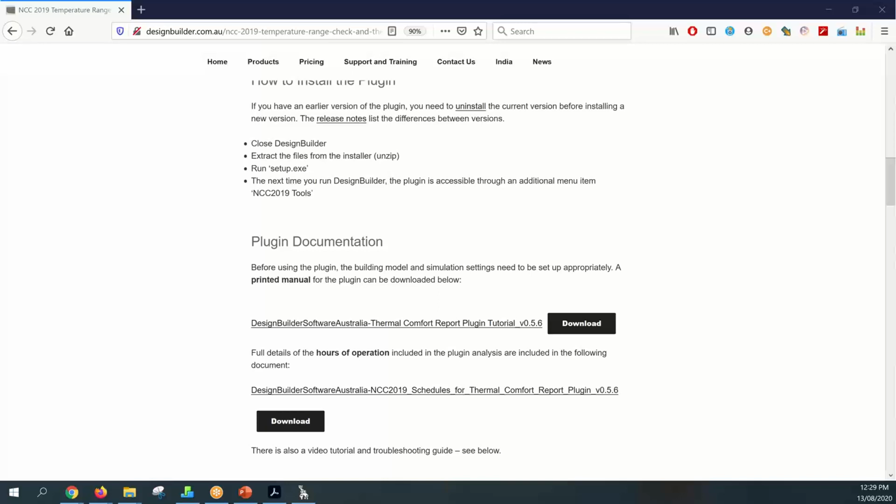Kareem, I think we can take that offline. After completing the simulation, graphs are not showing in the analysis. You probably have asked for simulations for hourly and not daily, and maybe the interval that's set in the screen is set for day, so you'll probably find that that's what it is.